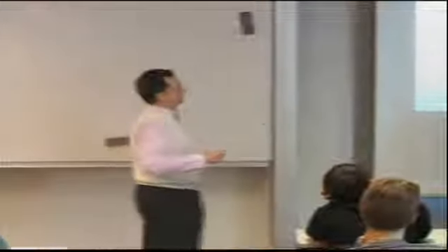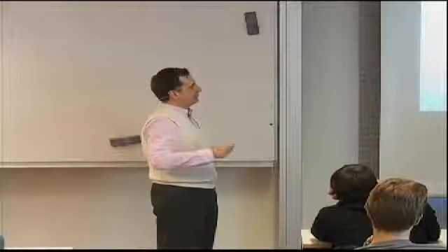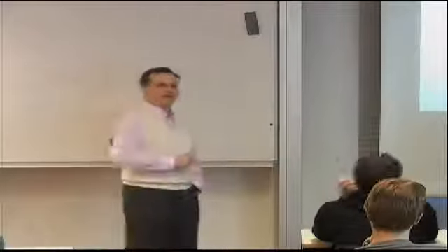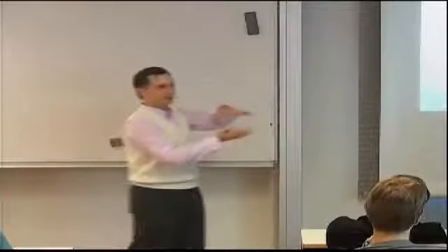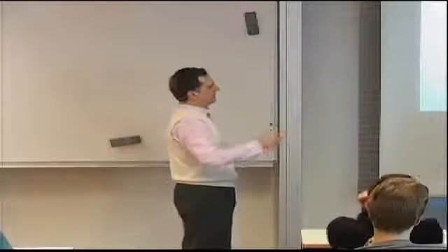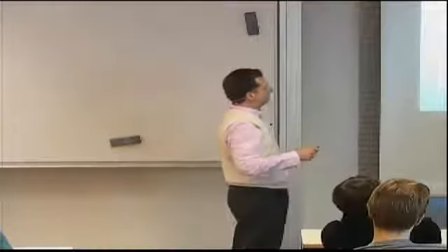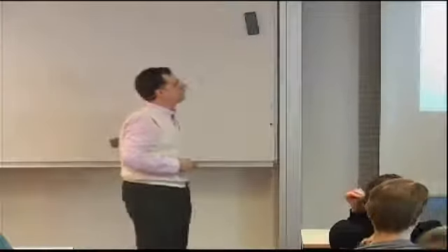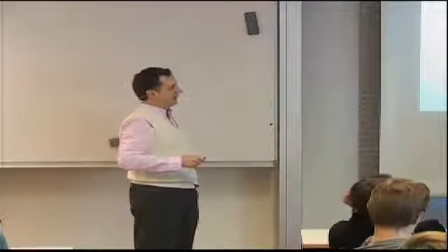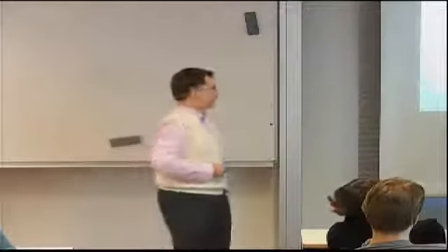We have a square panel here with dimensions of 200 millimeters by 200. It's clamped on this end, which means nothing moves in any direction. It's immovable on the top and bottom, which means there is no displacement in the perpendicular direction for these edges. And all around, the W displacement out of plane is 0, and we exert a load here of a little over 2 kilonewton. The material we use is plain weave fabric, so this terminology or notation should be familiar to you at this point.